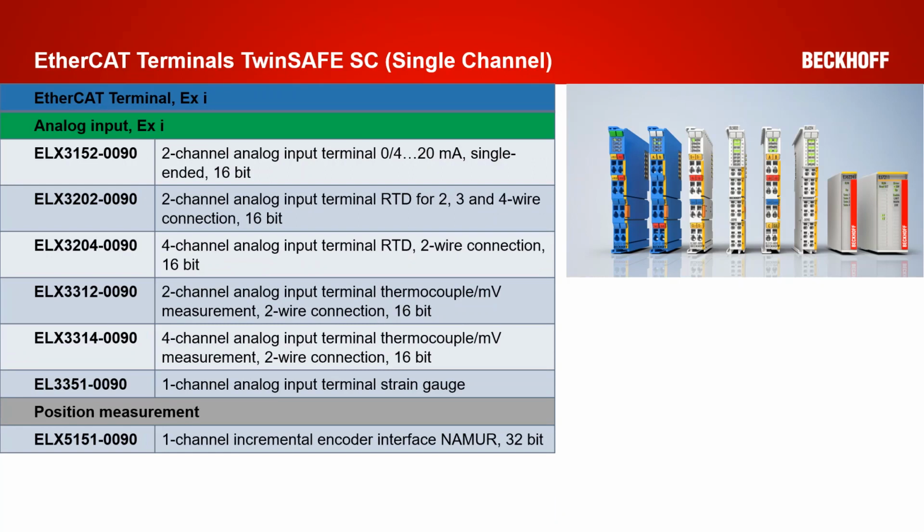Furthermore, the combination of our ELX terminals with the TwinSAFE single channel technology additionally presents a highly compact solution for applications with requirements for intrinsically safe signal transmission and functional safety. These terminals enable the direct connection of intrinsically safe field devices in the zone up to 0 to 20. Also here we have different signals like analog inputs and also position measurement signals with NAMUR interface.